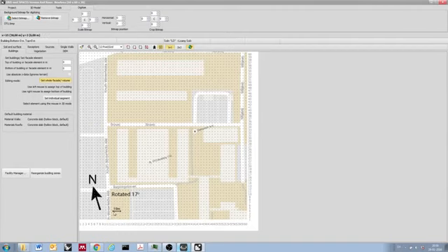Now, I want to make sure that my size is represented correctly in the ENVI environment, and my rotation of north is represented correctly. To do so, I will first try to fit my model to make sure my 10 meters corresponds to either one of these pixels or maybe 10 of these pixels. In this case I will attempt to adjust the size by 2 pixels.